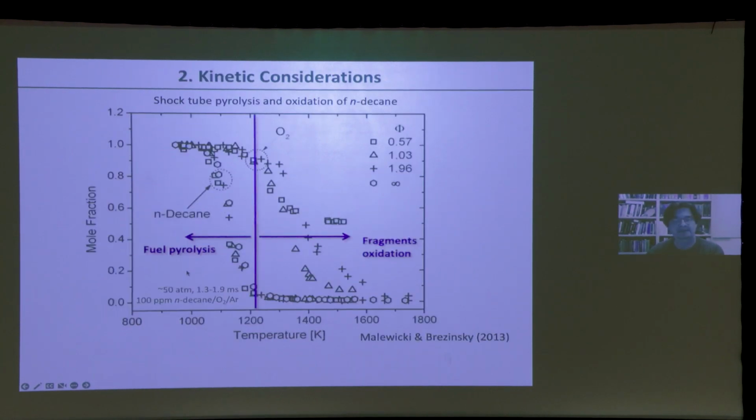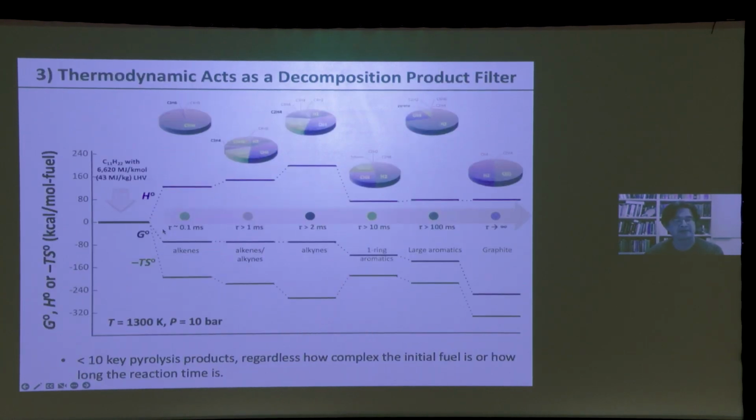And it is the entropy process driving the reaction, with always negative Gibbs free energy, to go to the final equilibrium product. Yet because enthalpy is working against you kinetically, the system gets stuck somewhere here. Somewhere here is where you find the dissociation products that you see in previous charts. Those involve hydrogen, methane, ethylene, some C3, C4 species. So this is the thermodynamics of this problem.